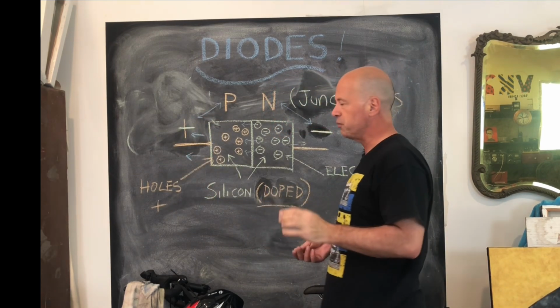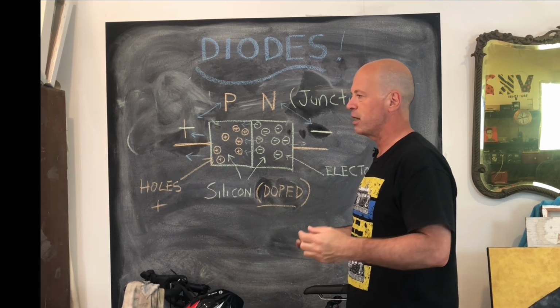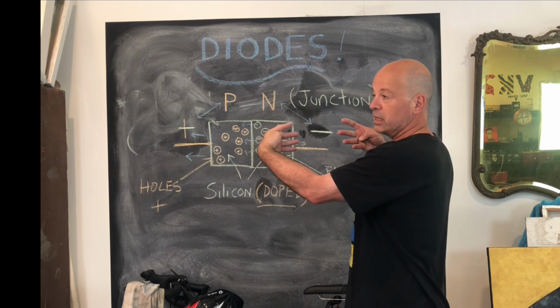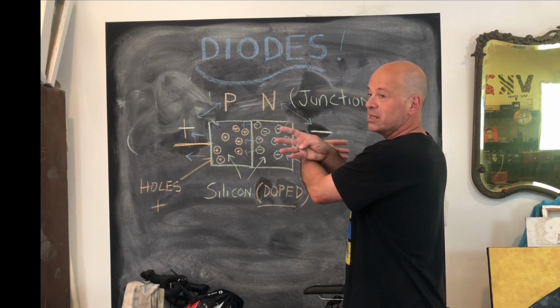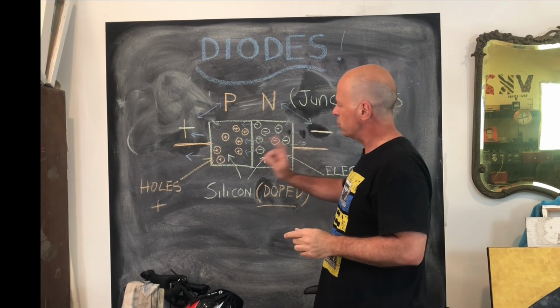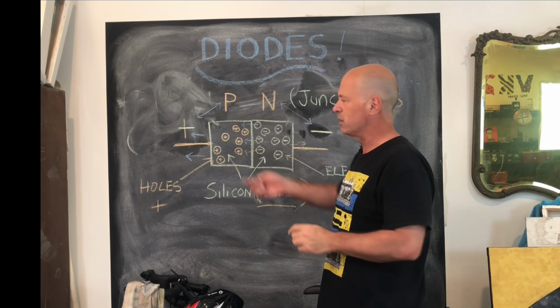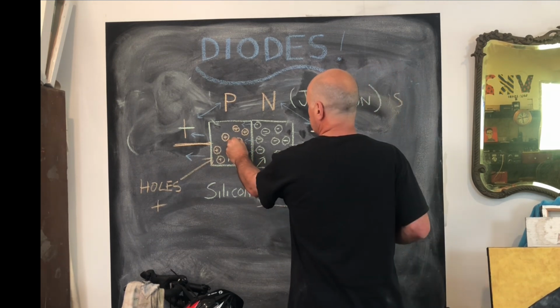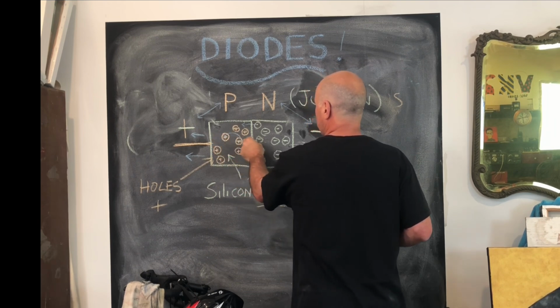So quite often when you talk about a semiconductor PN junction, they say that holes and electrons are flowing in the opposite direction when the thing is conducting. Now, that is true to an extent, but you need to remember that really what's flowing is the electrons. The holes look like they're flowing because as my electron jumps, say, from this hole into this one, it looks like the holes are moving in this direction.